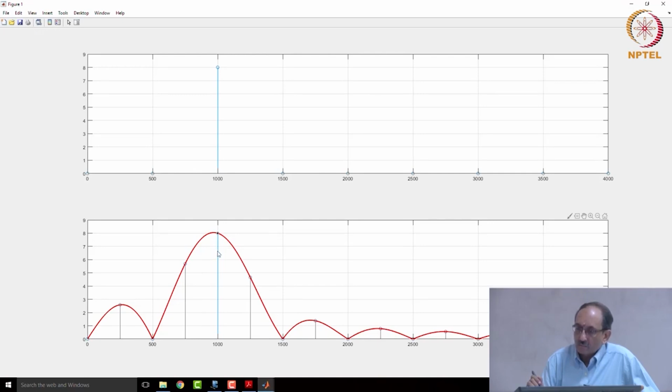Alright. If you observed more and more cycles of this sinusoid rather than 16 samples in which you observe 2 cycles, if you generated this sequence for say 64 samples and then zero padded it enough and obtained this picture, remember this is now equivalent to taking the underlying infinite duration sinusoid and applying a larger rectangular window, because now you are having 64 points.